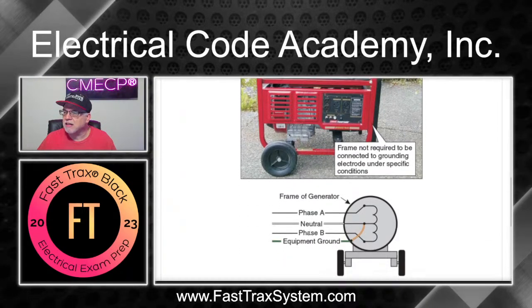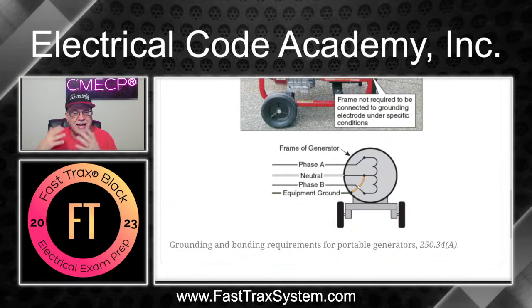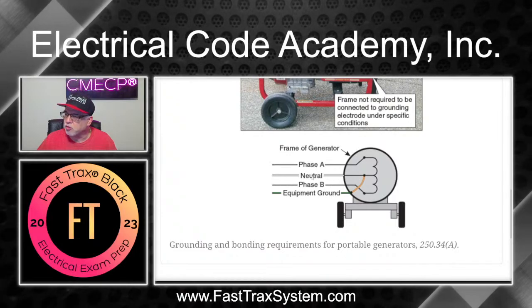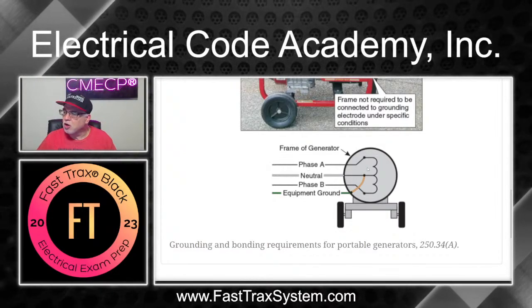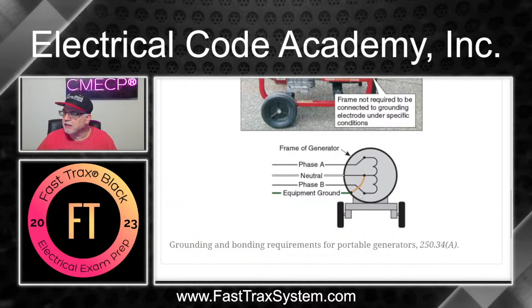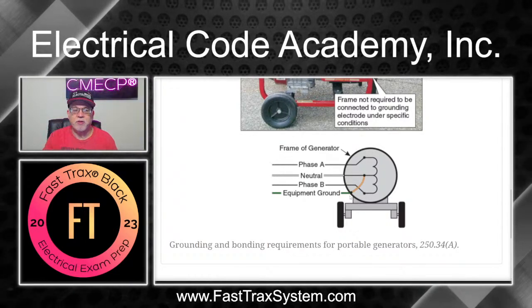What does that look like in an illustration? So here's that generator drawn out in an illustration. Here's phase A, here's phase B for the 240 volts. Here's the neutral. So phase A to neutral is 120, phase B to neutral is 120. Here is your connection right here that creates this bonded generator over to the frame. So the equipment grounds are connected to the neutral point. Everything in this frame is connected to the neutral point, all meeting the requirements that we just saw. No electrodes are required for this portable generator. Make sense so far? Okay.